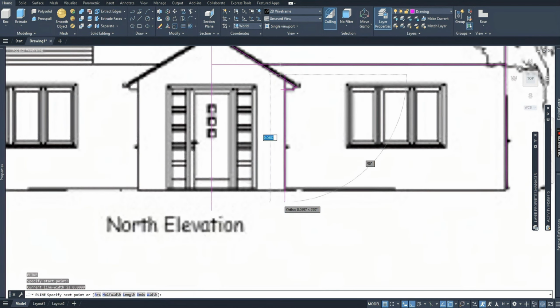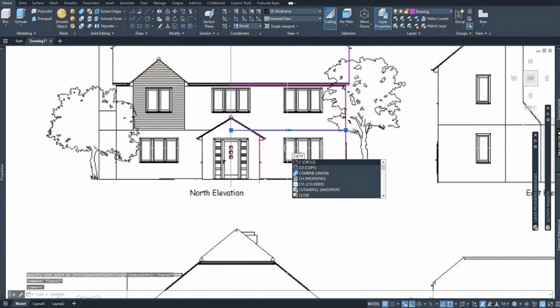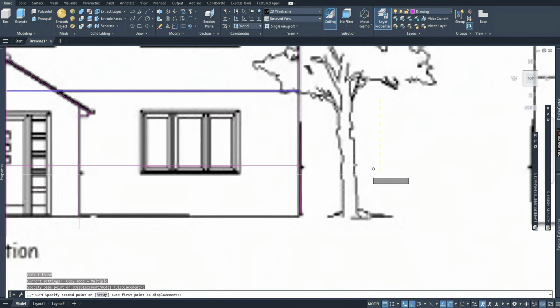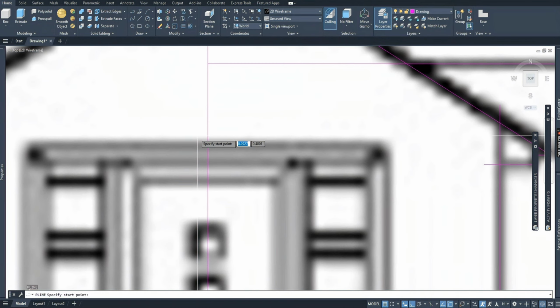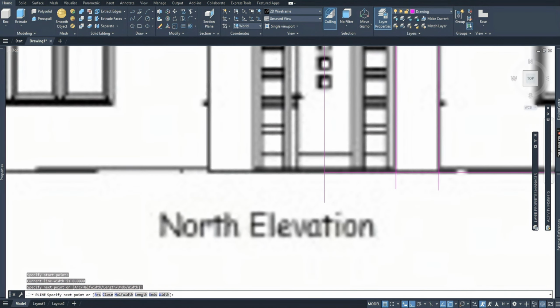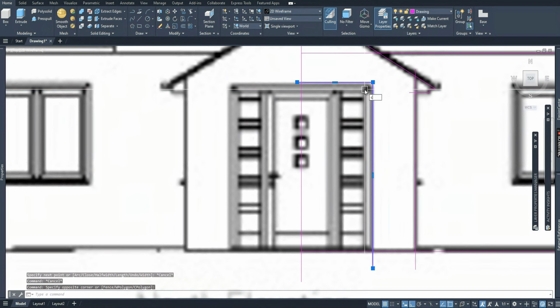Go back and I'm going to trim this drawing to make it suit. Just focus on drawing the lines that I need. That's my main focus right now. But what I want you to start to understand is just the process of creating polylines and how to edit them, and get to the point where you're confident using them in a sense.